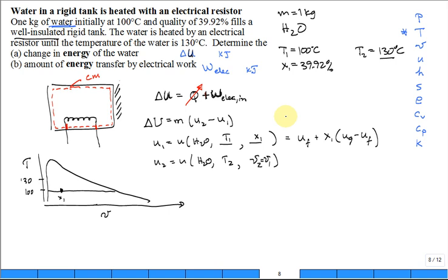How did you find V1? You just use the same type of equation as for u1. It's going to be V sub f at 1 plus the quality at 1 times V sub g minus V sub f. That makes sense? Thumbs up? You follow me?